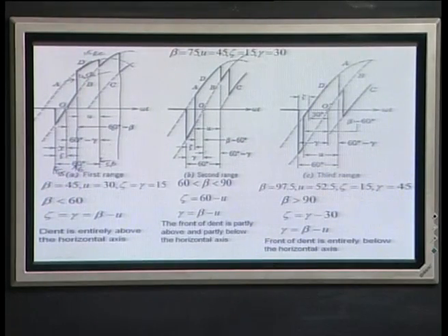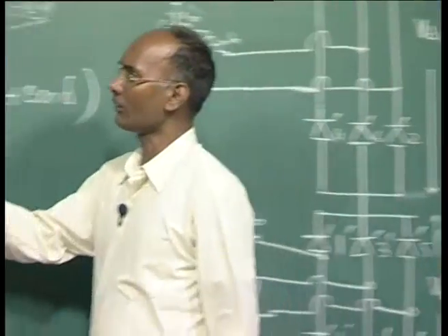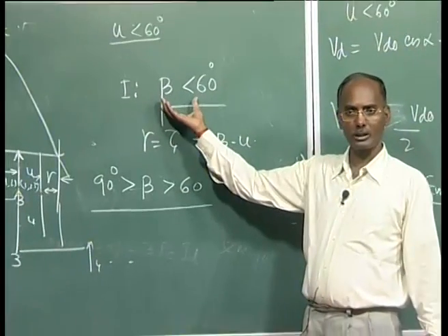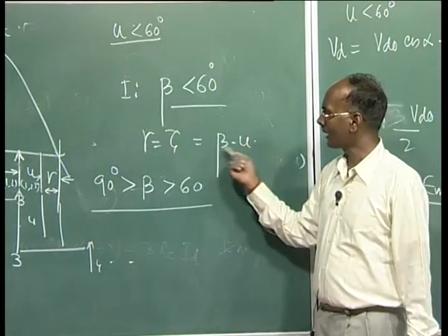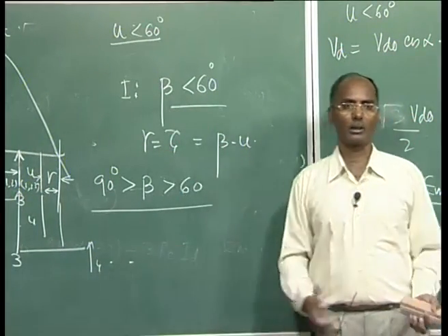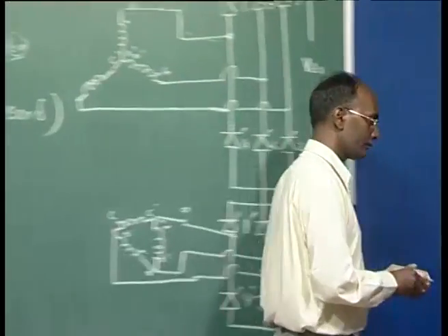So, this is very important, because we have to maintain the zeta rather than gamma. But in the normal case gamma is sufficient, because as I said, we are operating our inverters at less than 60 degree to maintain the reactive power support etc. So, in that case both are the same and our commutation is successful.